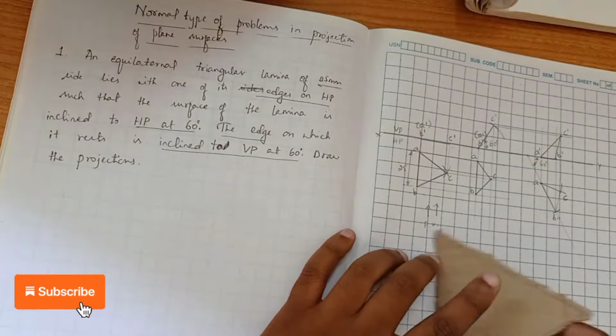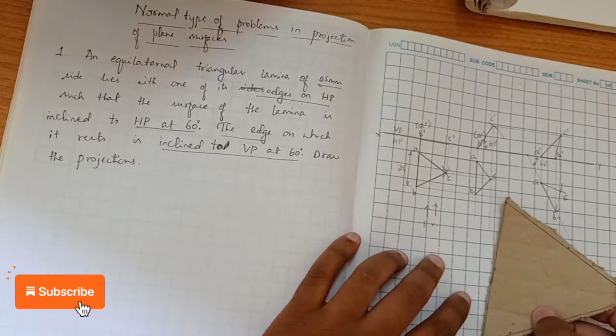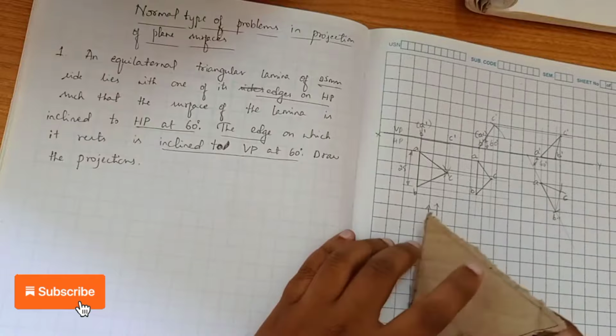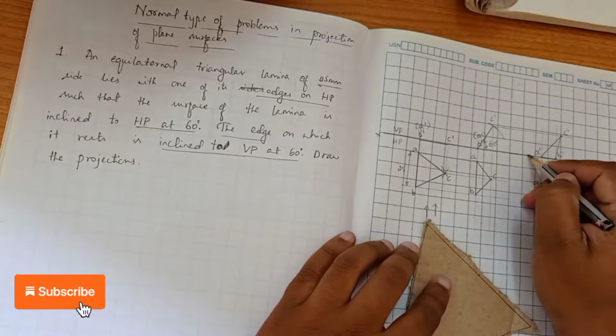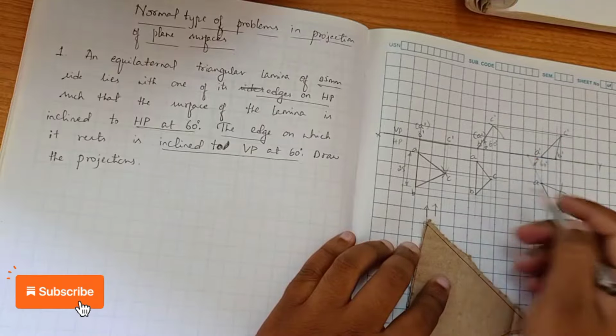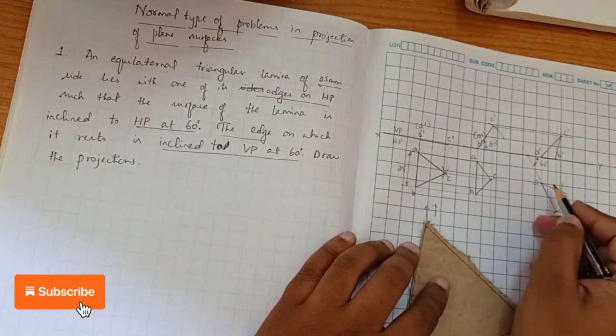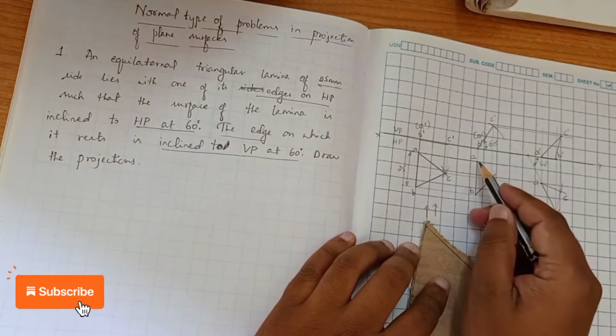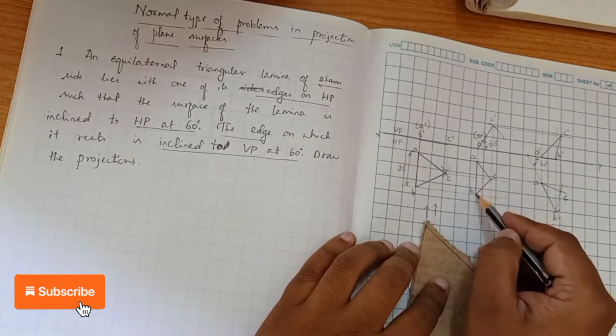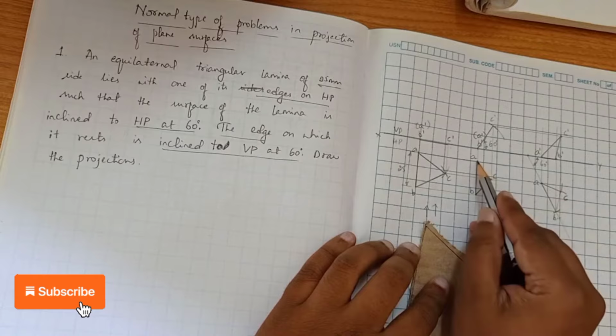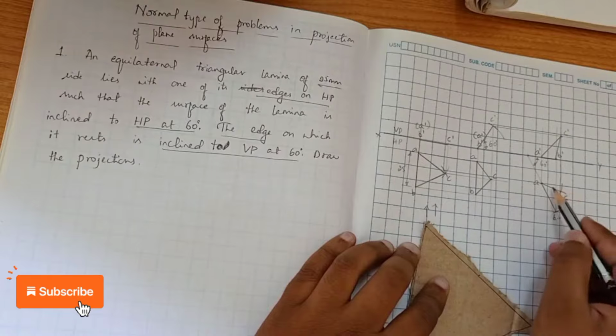Now in the third position what we did, so we have to incline this lamina by an angle of 60 degree. So for that purpose, first we mark a reference point, then we use the protractor, mark 60 degree, and then we draw an angle line. Then after that we mark a reference point A. Next we measure the length of AB with the compass and cut the arc. Then again arcs from A to C and B to C. We have completed the diagram.